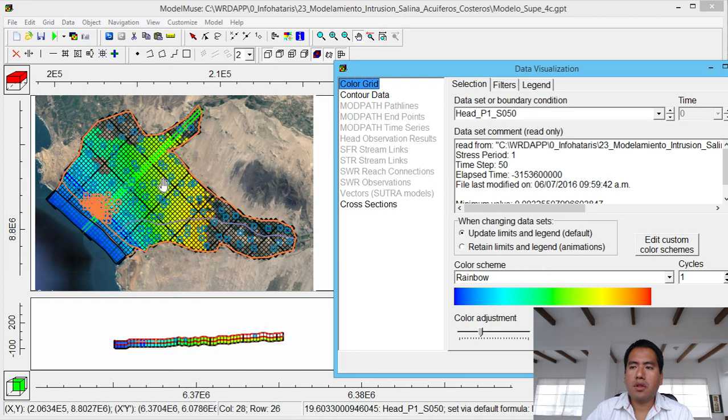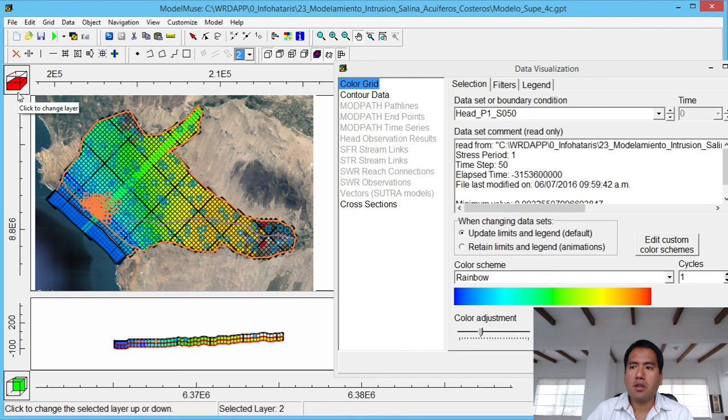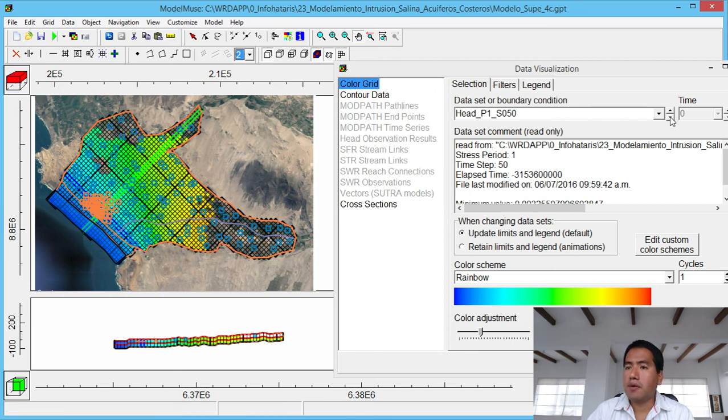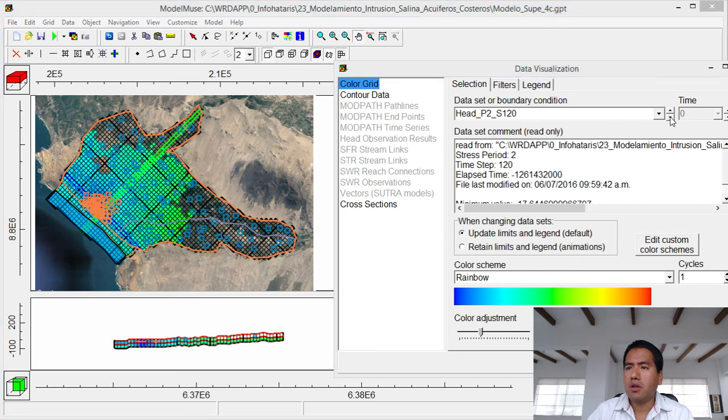At the beginning, you will have this distribution of the groundwater cells on the first layer. On the second layer, there is a depletion. This is at the beginning of pumping, for the first and for the second. But look, this is for the first, and this is what ends up after 60 years of pumping. We have a whole distribution, like we have a depletion, like many cells that were actually active went dry.